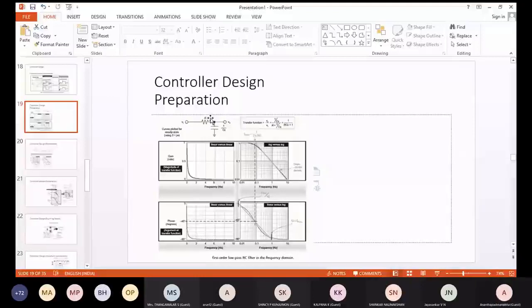That's why all these power converters, since we are using energy storage elements, are not only for power conversion, they are also for filtering. Okay. So if you take any power converter, you will have L and C. So it is supposed to be a second order filter, filtering all the high frequency components and allowing only the low frequency components to come out.